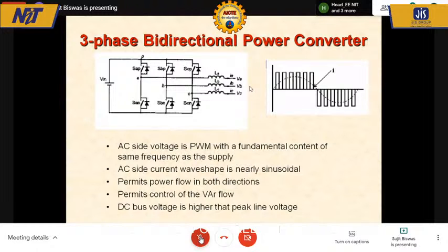So what is the remedy? You do connect a capacitor here, but after the capacitor, put another reactor to detune. So you will land up not using an LC filter, but an LCL type of filter. That is the reason why we use an LCL filter, because you have to detune your system, to prevent taking any risk of going into a resonance with the system.